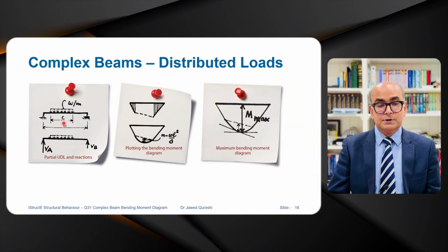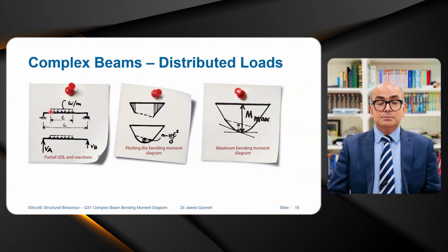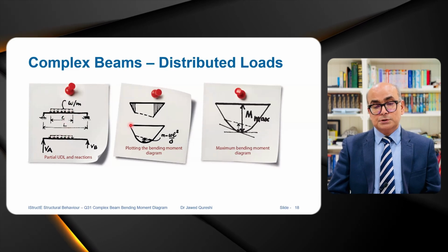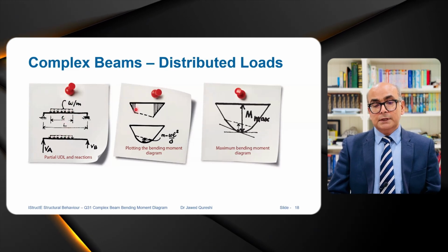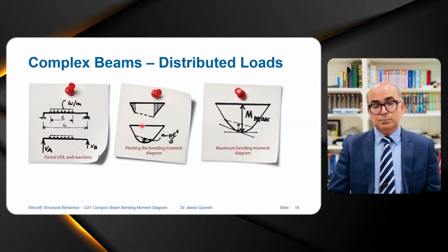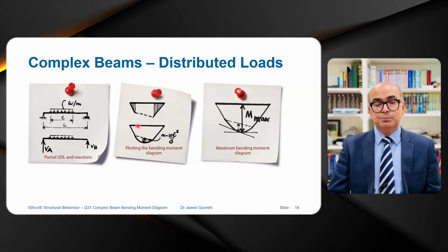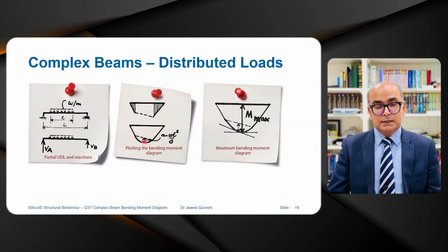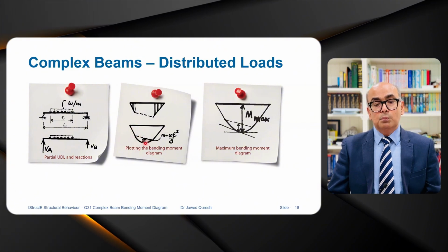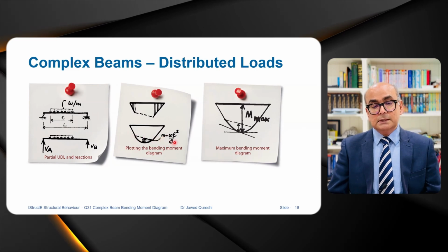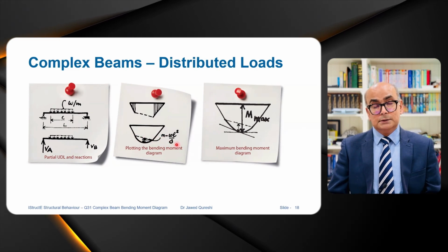So if it was a straight line here, and distributed load is applied only on this central portion, when we apply loading, the end moments will be like this, but the portion between the start of UDL to the end of UDL will be curved. The other portion will be straight lines. The moment between the line connecting these 2 points will be WL square over 8.